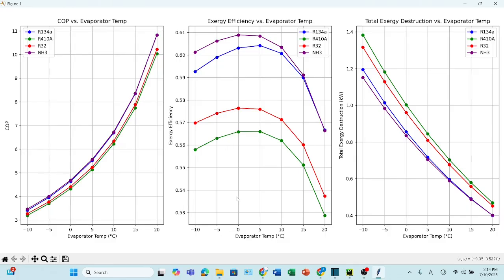And this exergy efficiency is an important concept when we include the ambient temperature, because the first law doesn't include the boundary where your system is placed, it does not include the heat transfer with the surroundings, and it does not tell you the details of the losses and irreversibilities going on in the system. So this is the advantage of knowing the exergy efficiency and total exergy destruction.